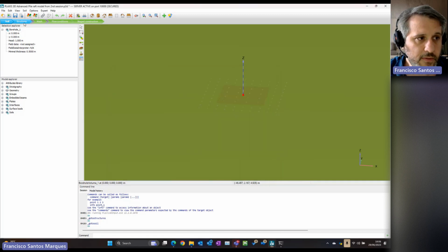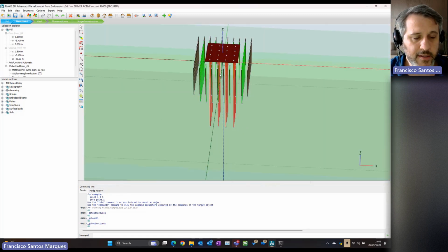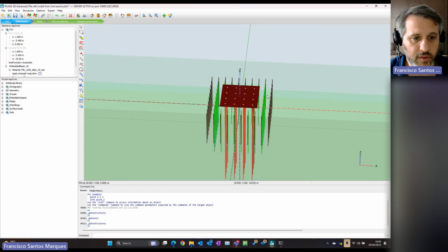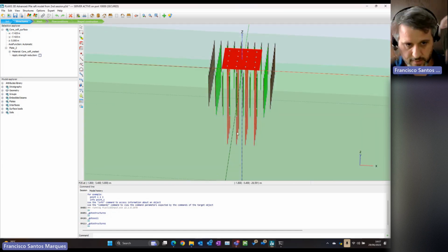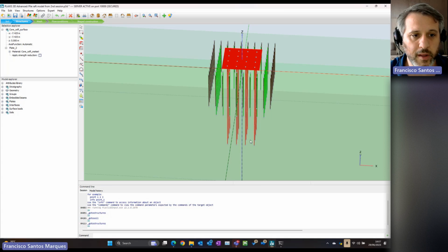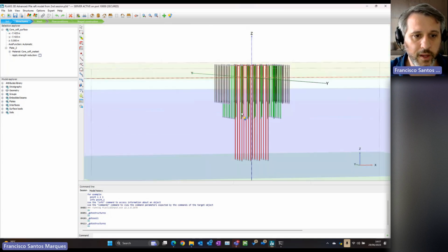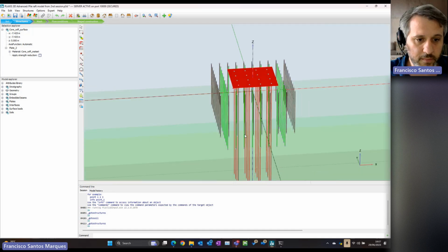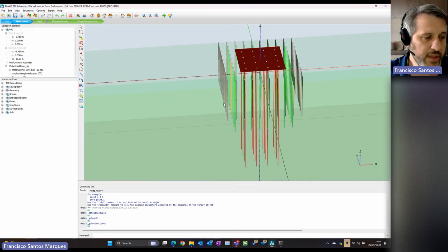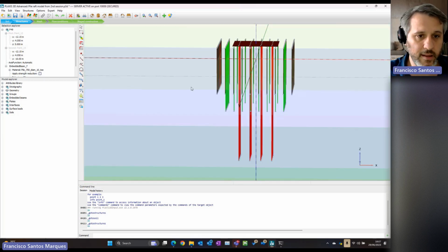So we have the typical Made Ground, gravels, London Clay, then Lambeth Group and Thanet Sands, followed by chalk. The whole idea here is that if we have a piled raft and we assume that most of the load is going to be applied on the core, this small rectangle here, the core area, this is where we expect most of the piles to be longer. The further we get from the core, we're assuming that the piles reduce in length and in diameter. So we have 1200 millimeter piles, 900 millimeter piles and 750s, with different lengths and diameters.